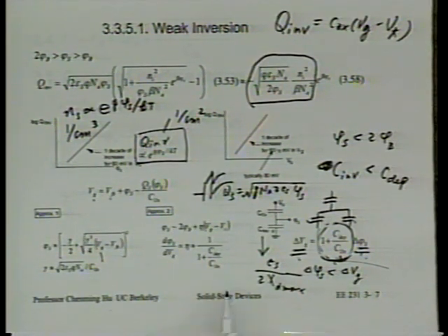And from those two extreme cases that I reviewed with you, you can always figure out what this form is. Should C depletion be on top, or should C ox be on top? Should this factor be on the delta Vg side or on the delta phi s side? Just from those two special cases, you'll be able to figure out, all right? But just remember the general shape is 1 plus C depletion over C ox.